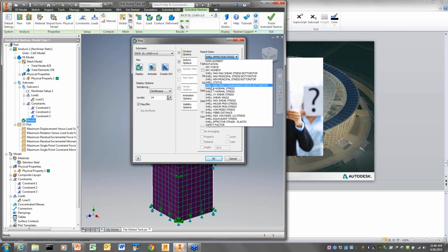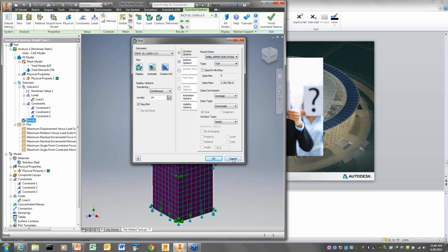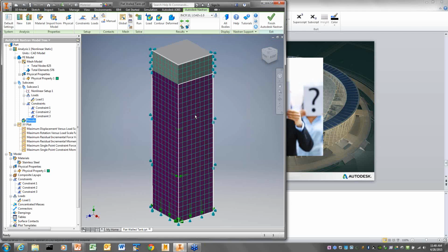So it'll give you a mesh convergence error after you've run it, and the method of that is simply comparing element A to element B. Say element A says it's 10 psi and element B says it's 100 psi, so they differ by 90 psi. So along that boundary between the 2 elements, you have a 90%. It's not necessarily a 90% error, but you have a change in stress by 90%. So that's one way to check the convergence.